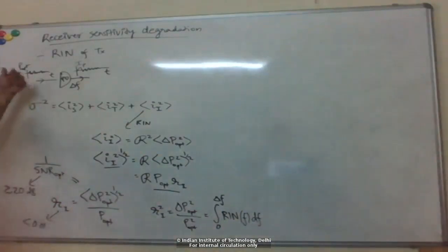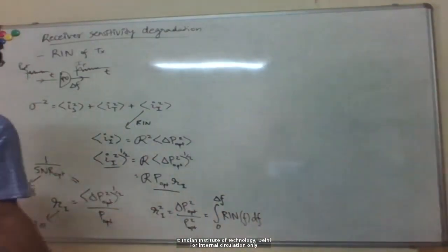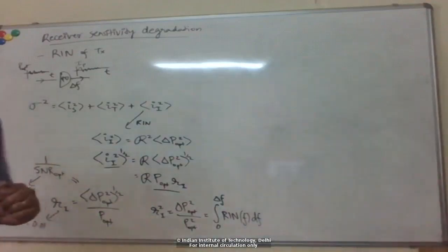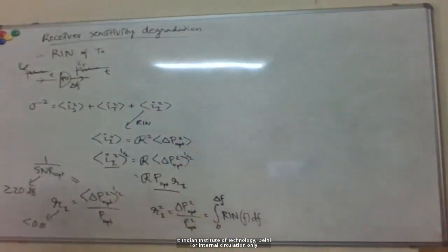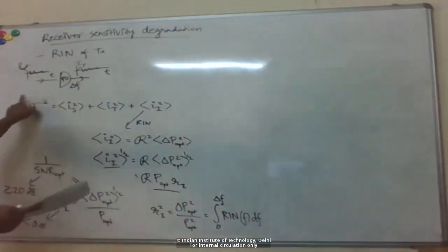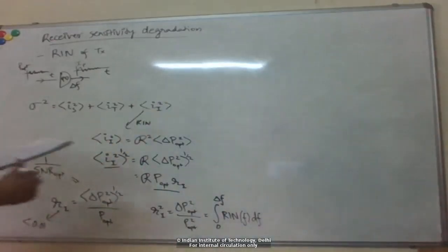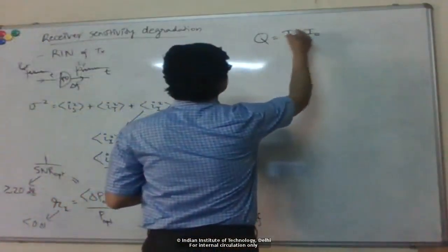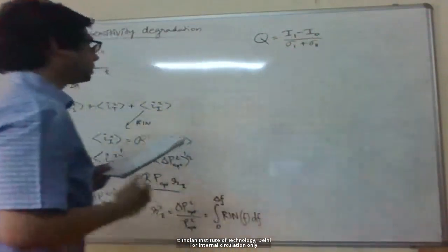If you take a good single frequency narrow linewidth semiconductor laser in the market nowadays, typically that's the level of this optical SNR due to the RIN noise. So how does it impact our link? You can see that the noise current has gone up due to this extra term. Again, if you look at this Q factor, which is the difference in the currents between bit 0 and 1 divided by the sum of the RMS noise currents.